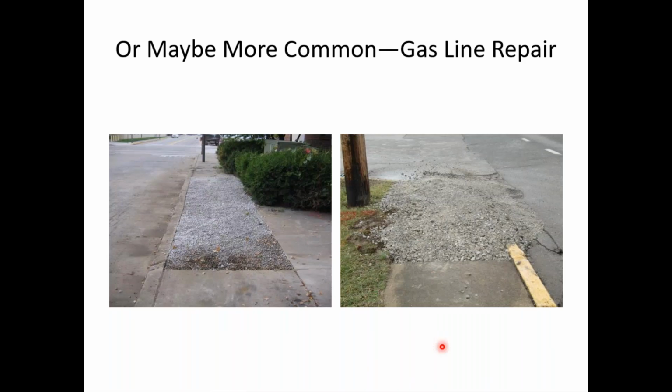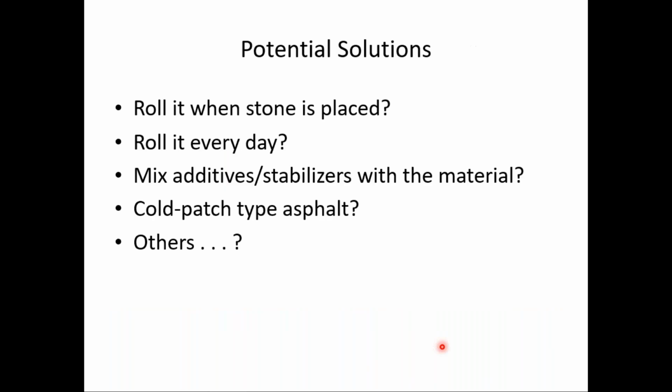And so sometimes I get comments like, well, on the left there, if they had just rolled that when the gas company left, that would be accessible. And I sort of take exception to that. It might be accessible for a short time after that stone is rolled, but as weathering takes place, as traffic passes over that sidewalk, the stone is probably not going to remain firm and stable, and so it may not be an accessible surface for very long.